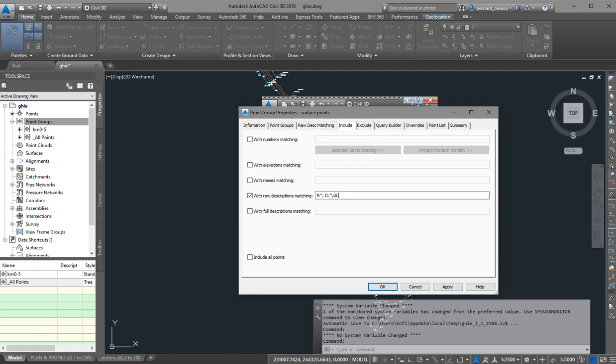GL. Good. The GL too, let's add an asterisk to it. In this particular data, you see there's a point called GLF. That's ground level that were picked in farms. So I told them to code it GLF. So at least when we are doing the design, we have an idea that there's a farmland here, so you know how to save it and minimize property impact. So GL asterisk. Then what again? Is that all? I think that is all for now. So just these three, the R, the CL, and GL asterisk.